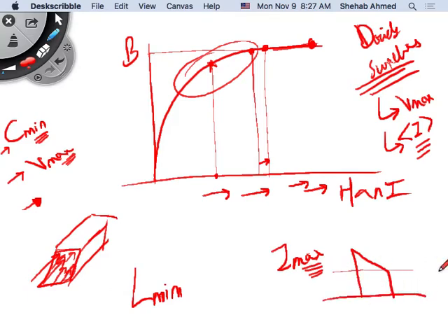So I will calculate this average current because it's an indication of how much heat is going to be dissipated in the switch. Right? The power loss in the switch is the voltage times the current. The voltage across the switch and the current through the switch. So it's the average value of current through the switch that's going to cause the temperature to rise. Right? So these were the two parameters for switches and diodes that we started with.